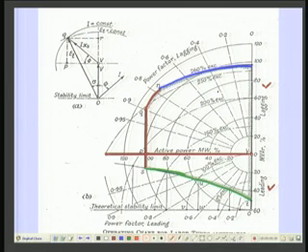In fact, this horizontal line shows the situation where the phase angle between the terminal voltage and the internal voltage becomes 90 degrees, and that is, we cannot operate when the power angle is more than 90 degrees, right. And this graph is plotted considering a stability margin of 10%, and therefore, the operating region is inside this curve which is shown here, which has 4 different segments.